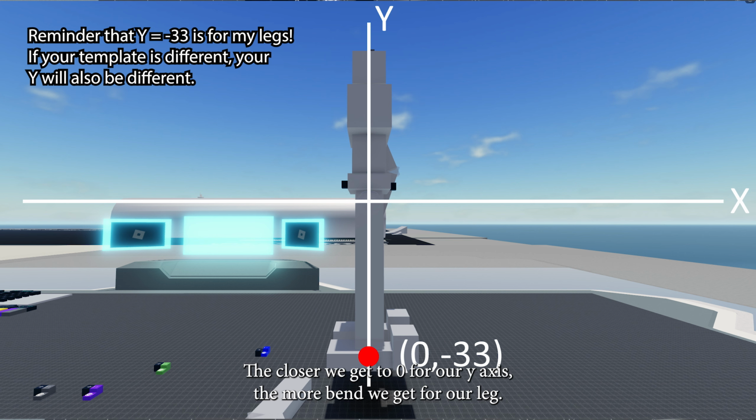Let's say you want to add an offset to the leg so that they are slightly spreading their legs instead of just standing straight still. What we can do is add offsets to the x coordinate to spread the limbs. To know which axis you need to apply the offset to, go to the frame and see the orientation of the global to relatives. For example, since this global to relative has a z-axis facing forward and the y-axis facing upward, we can assume that the positive x-axis is towards the right.